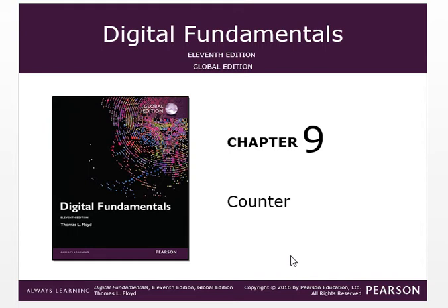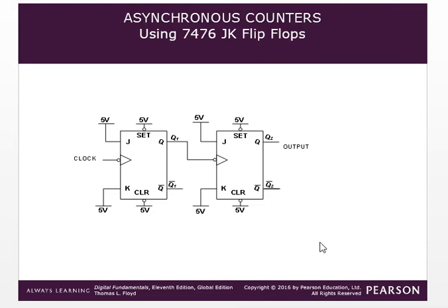Last week we studied different types of flip-flops: JK flip-flop, SR flip-flop and D flip-flop. And now this week we are going to study the applications of flip-flops. I already told you last week that one of the applications is the counter. So what is this counter? If flip-flops are connected in series, then it is called a counter.